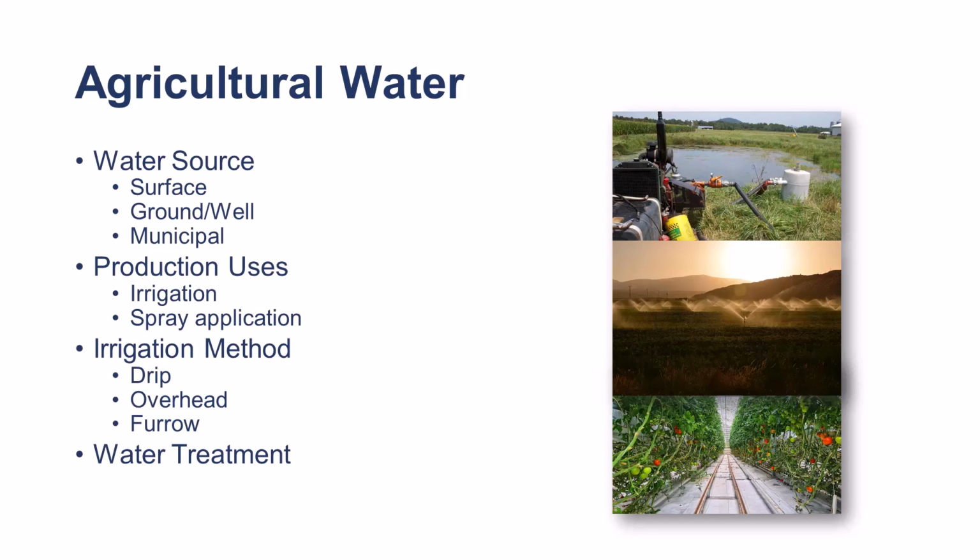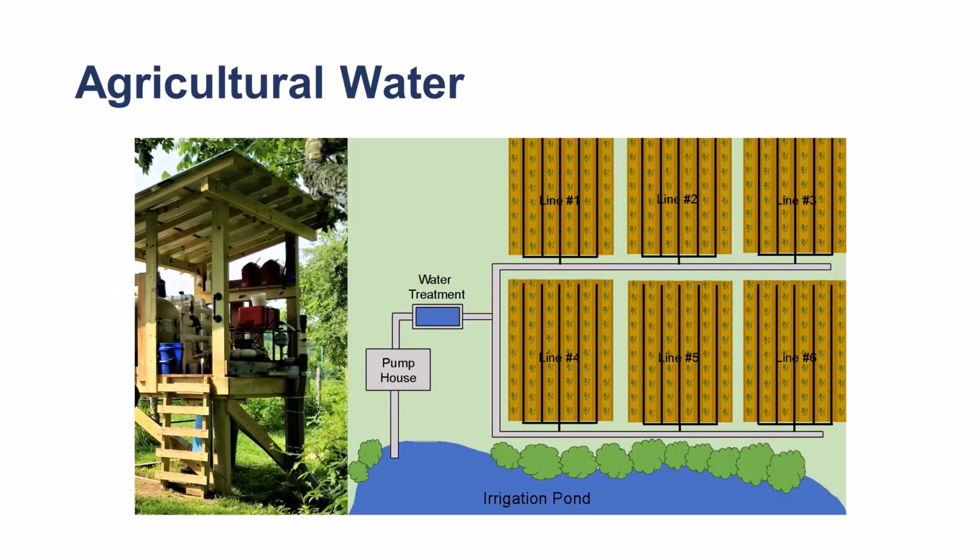Addressing these factors will help in identifying the potential levels of risk and possible control measures you can take moving forward. Similar to the activity we did in Module 1, hazard analysis, we will want to sketch the general layout of your water system and the flow of water. Include features such as irrigation source, pumps, backflow prevention devices, treatment equipment, and other above-ground features.